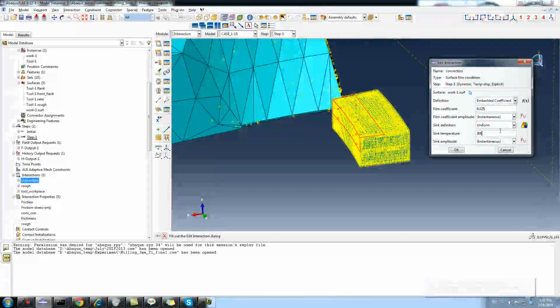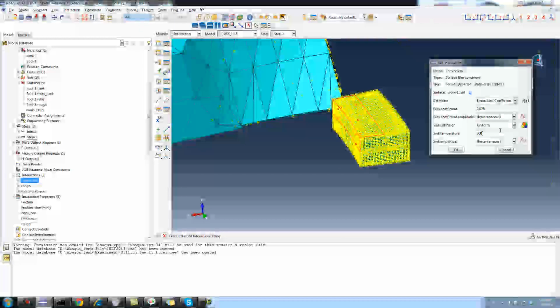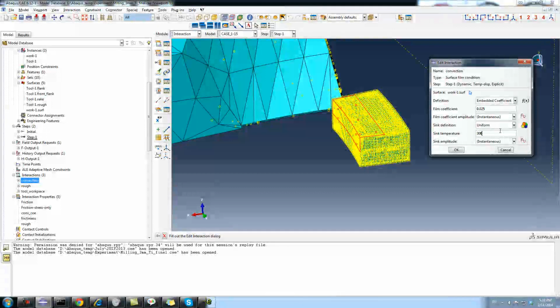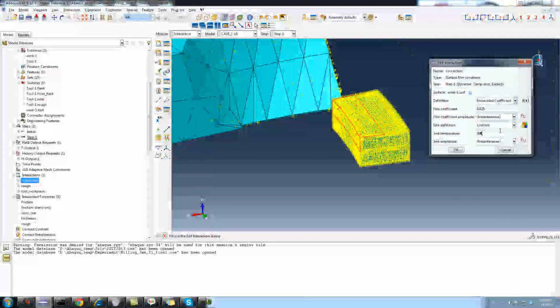Make a copy and write all the units, the same units, because if you miss them, it will be difficult. And mostly try to use Kelvin because it does not go negative, and you cannot put negative values here. So try to use Kelvin. Convection.